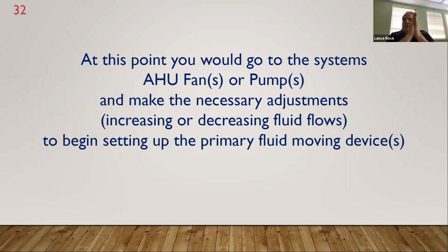A lot of people like to operate and think they're saving money by slowing the fan down. But in reality, if you have a chiller system with VAVs and pumps, you have a simple thermostat or temperature sensor, just like your house. What dictates how your system operates, heating or cooling, is your thermostat. Your thermostat dictates how often it runs in the summer, how often the furnace runs in the winter. The same in a building.